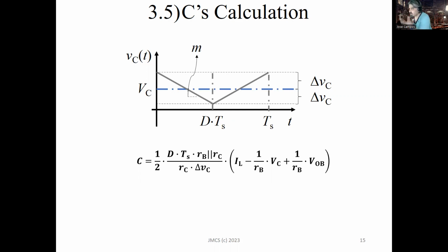So with this equation, we can calculate the L and C for this converter. It's important that you know that this converter includes trace resistance, so it's not an ideal converter. Instead, we can try to do the same with an ideal converter, which does not take into account this resistance. You should keep in mind that this algebraic manipulation could be harder in comparison with an ideal converter.